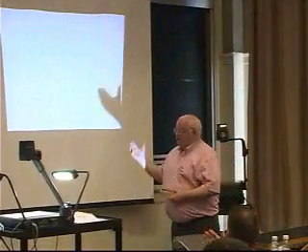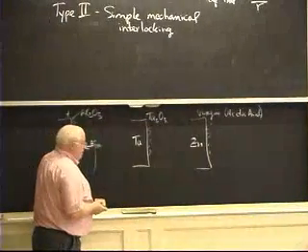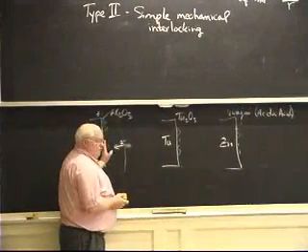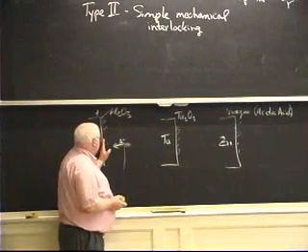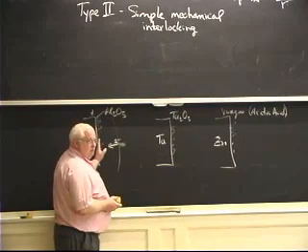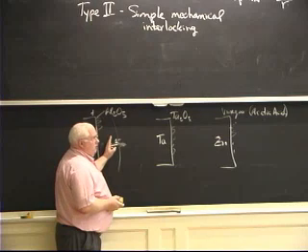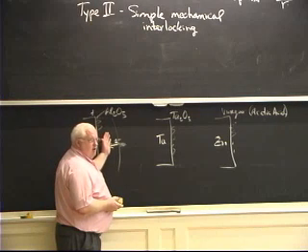Well, when you anodize, you're growing that oxide layer faster than you could ever do it in the real world. You're using electrical energy to grow that oxide very rapidly. Ordinarily, that aluminum oxide will form a layer that's like 10 nanometers thick. And you want to grow something that's 1,000 times thicker. Well, you'd have to wait 1,000,000 years to have nature do it as the oxygen diffuses in.